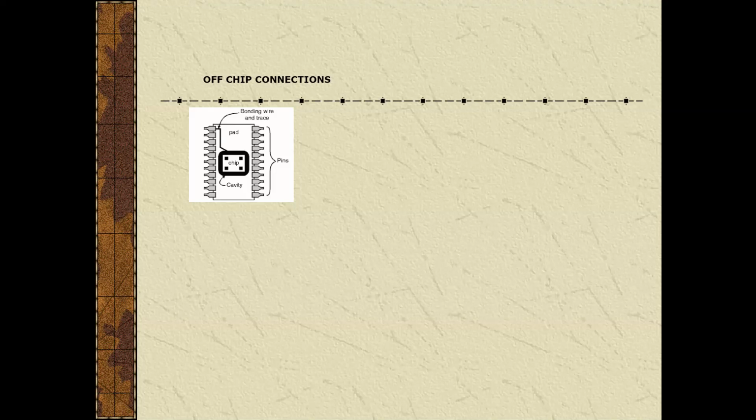Here is the generic package for an IC. The packages also have electrical problems which are caused by the inductance of the pins and the printed circuit board attached to them on the chip wire. Further, package inductance introduces significant voltage fluctuation. Then IO architecture and pad design.